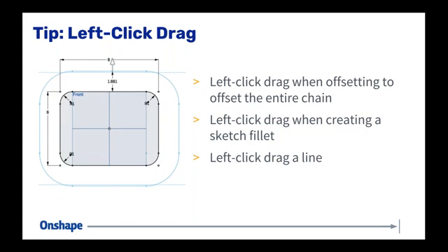If I go with assemblies, then how can I use configurations? Any way I can use configurations in the assembly? No. Good question. Today we do not have assembly level configurations, but that is what I would call one of our biggest priorities in the company. So if you need configurations today, you must use the Part Studio, but we are definitely aware of the need. I would say it is, again, one of our biggest priorities.